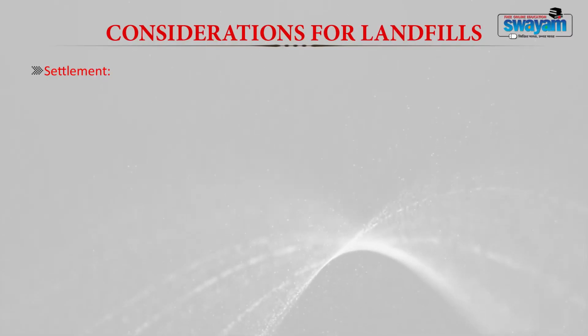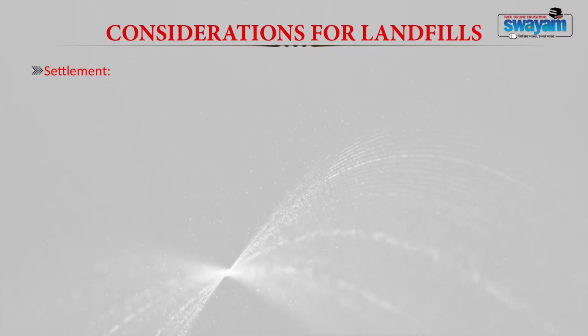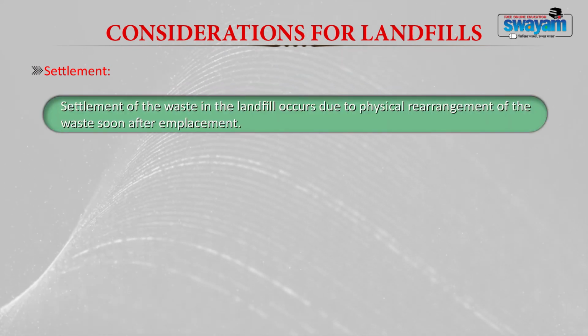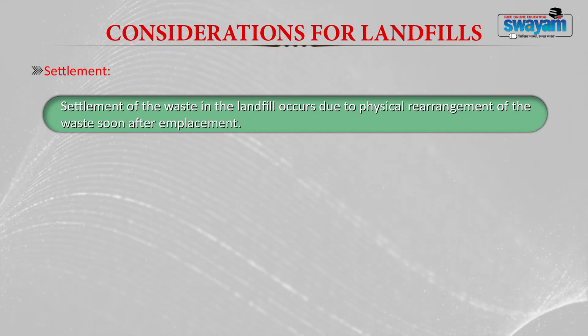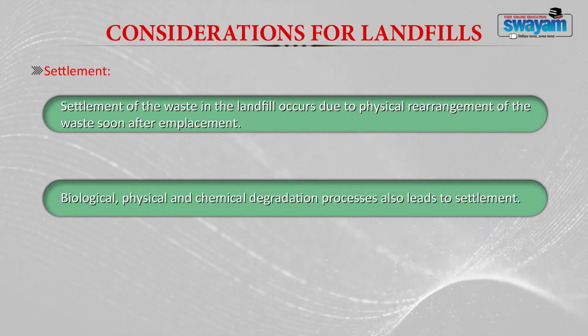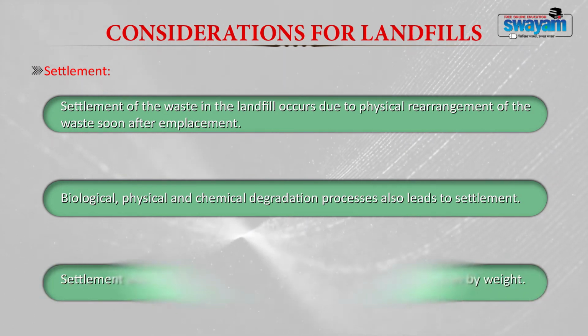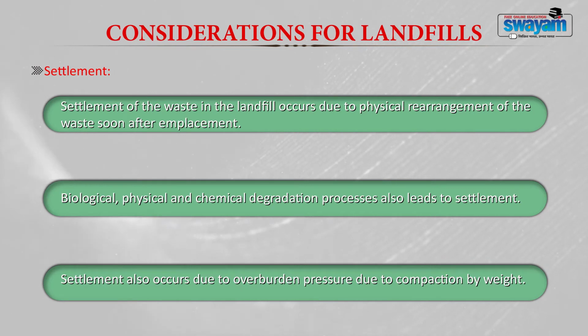The next important factor which you have to consider while designing a landfill is the settlement. Now, settlement of waste in a landfill occurs due to physical rearrangement of waste as soon as you place it in the landfill, then due to biological, physical and chemical degradation processes, and due to the overburden pressure from compaction by weight. I mean, if you place waste layer by layer one over the other, the top layers will create a pressure on the bottom layer, because of which compaction will occur. This also results in the settlement of waste.